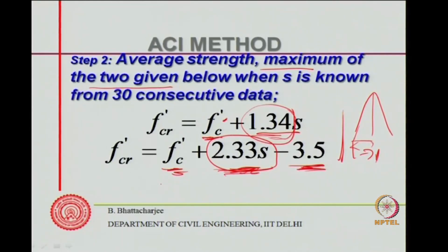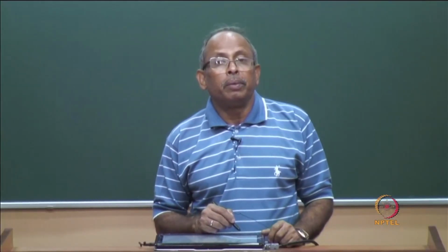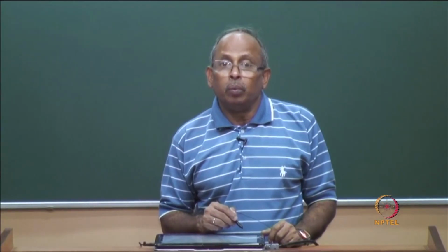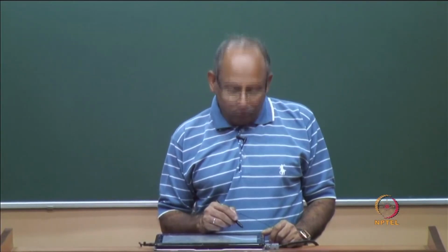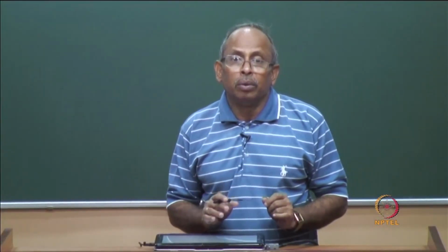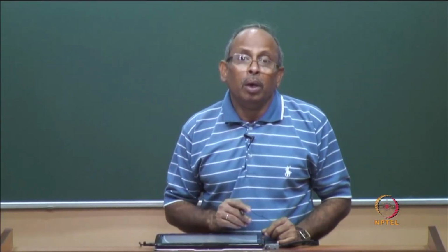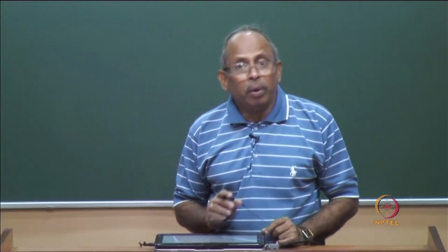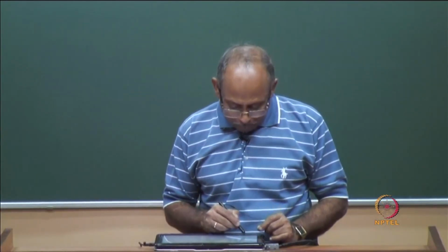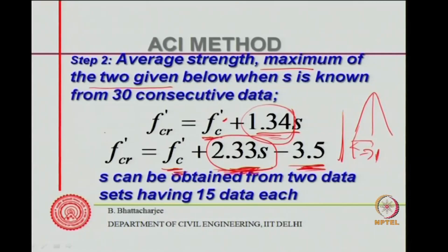the water cement ratio. So, you can find out the water cement ratio, and we have also found out the water content. Again I repeat, this is all for the cylinder strength. So, average cylinder strength is known, and therefore, correspondingly I found out the water cement ratio. And when I found out the water cement ratio and also the water content, I should be able to find out the cement content.